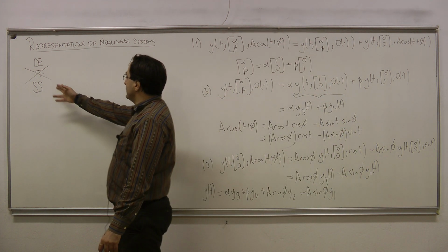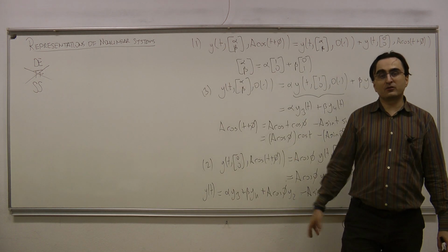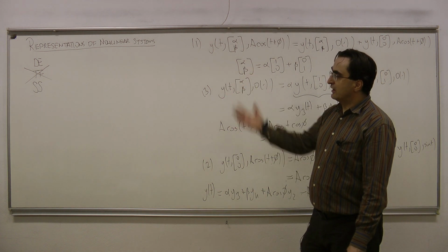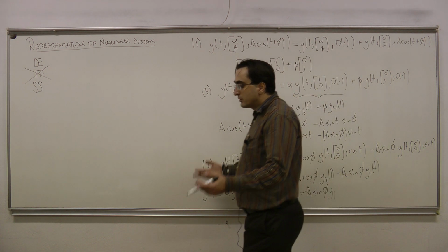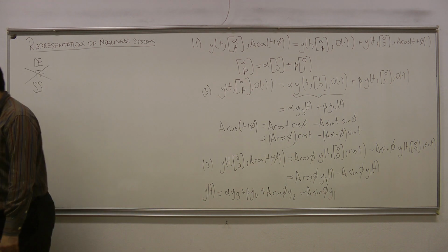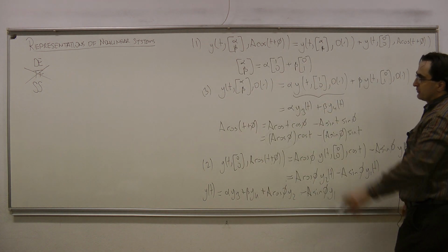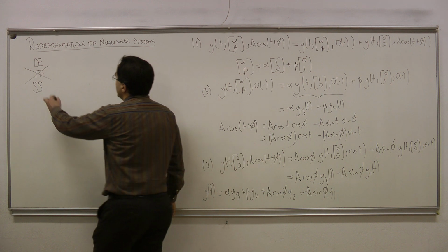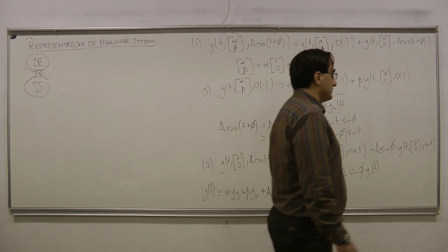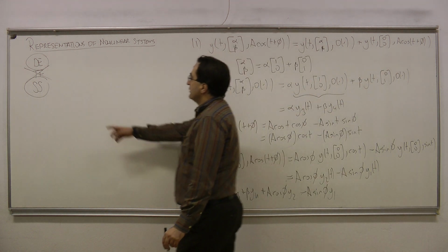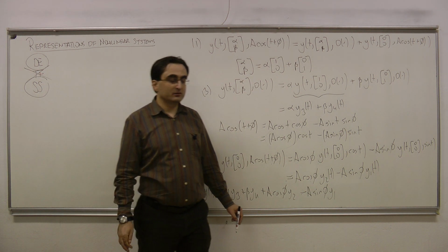Okay? So for nonlinear systems, really we cannot use the Laplace transformation to obtain a representation for that system. In general, a nonlinear system doesn't have any transfer function representation because Laplace transform cannot be used in obtaining a representation for a nonlinear system. So we lose one of the representations, and for nonlinear systems, we have two types of representations: differential equation and state space representation. We know that transfer function was a Laplace domain and a frequency domain representation somehow.